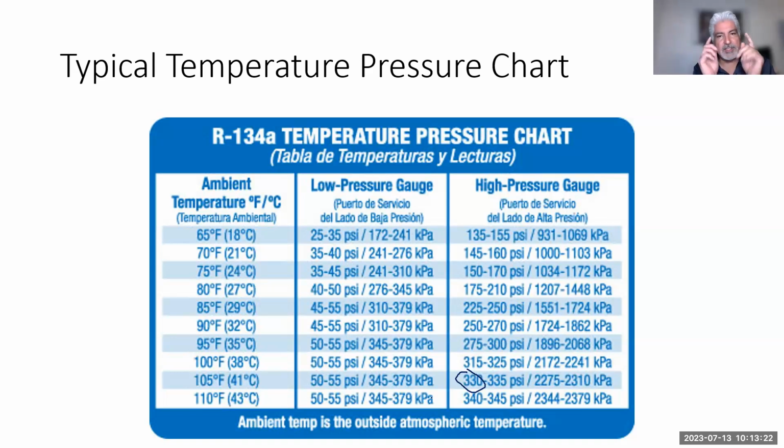Your job, again, is to do that voltage drop test that I mentioned earlier, to ensure that clutch has no unwanted resistance in its circuit, so it gets the full amperage it's supposed to get. Now, you can go ahead and put an amperage gauge, an ammeter, on one of those wires, but I prefer you do a voltage drop test, because that is telling me if I've got unwanted resistance in the circuits or in the relay. Okay, can't stress that enough. So definitely put a voltmeter across it, because these poor compressors are getting beaten.